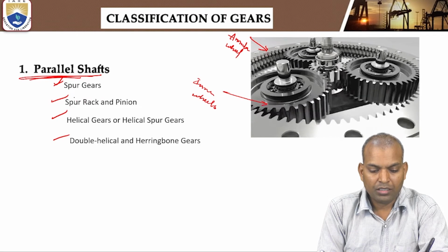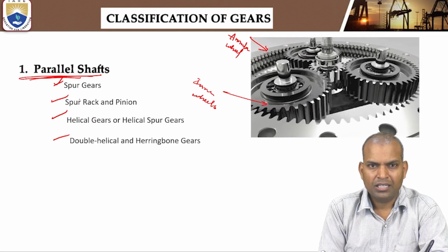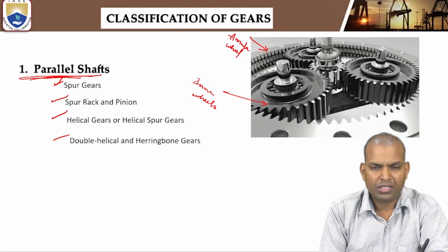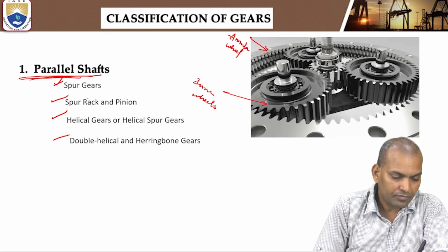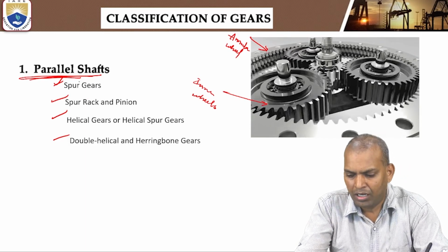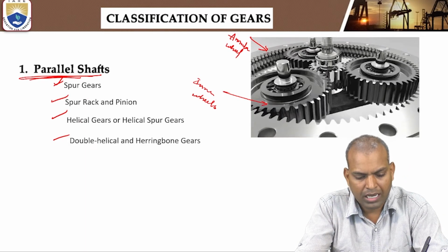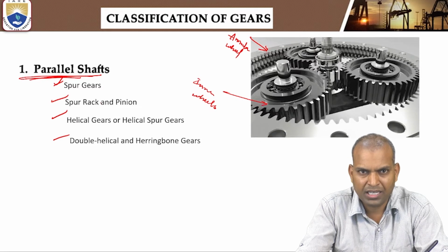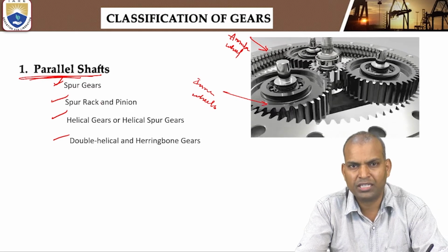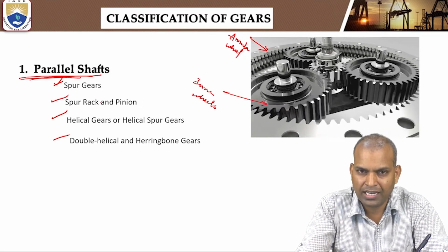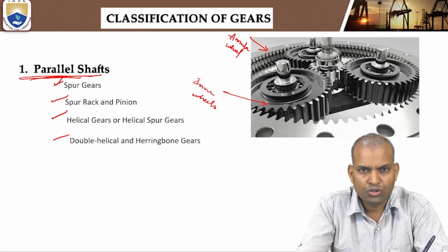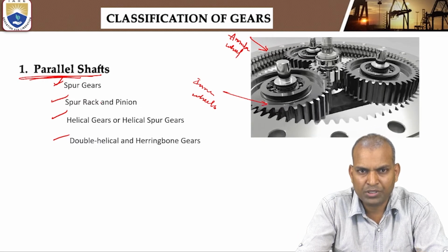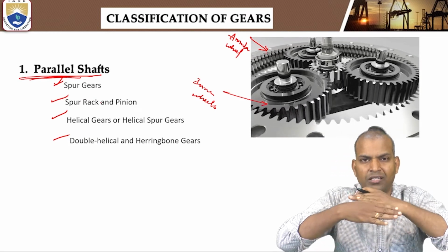And whereas here helical gears, in this helical gear it is a single helical gear, and both shafts are parallel to each other. One of the shafts has teeth in one direction, with some inclination, helical. That angle is known as the helical angle or helix angle. Another gear, the pinion, the opposite wheel or driven wheel, has teeth in the opposite direction such that they intersect each other.